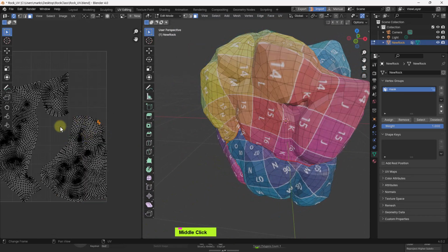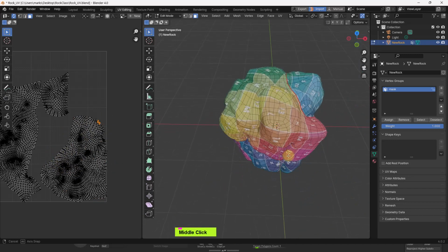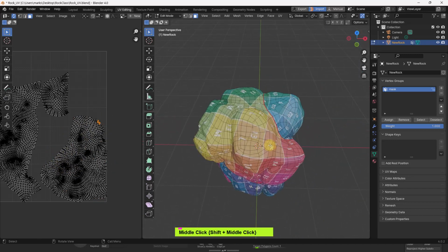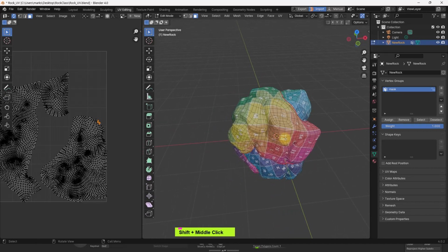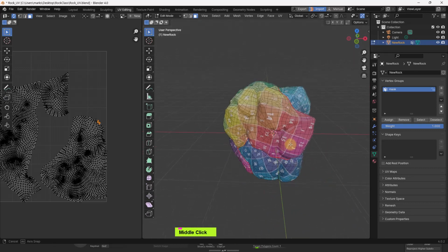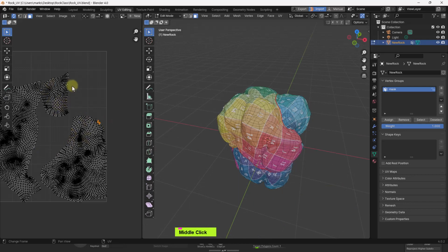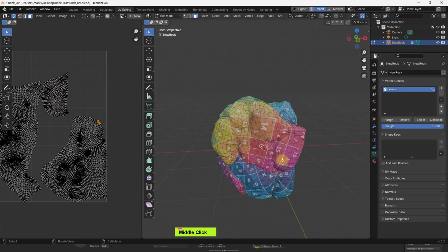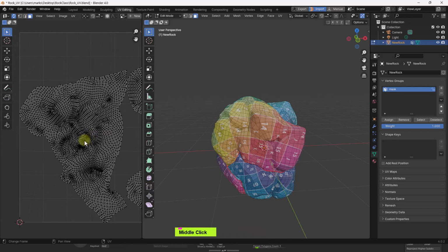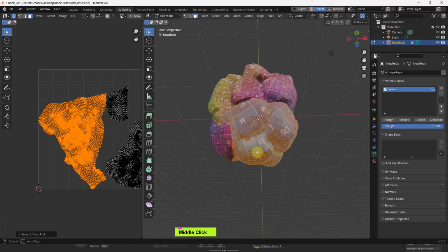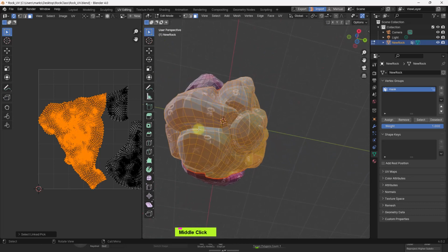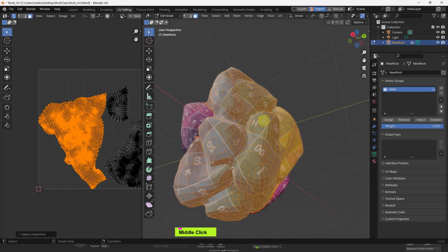So if I wish, I can go down deeper and cut this up further. You can actually go as deep as possible with the holes, and cut multiple pieces. The more smaller clusters you make like this, the more precise the texture will be. Okay, so there will be less stretch, but of course you will end up having more seams. But because the seams are not that visible, it won't be that much of an issue. So this cluster, this part, is still stretched a lot at the bottom, so we definitely have to cut through